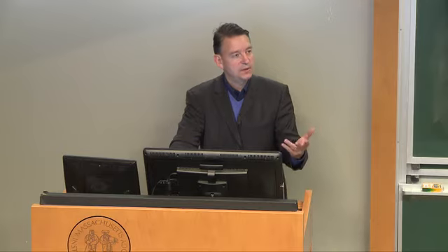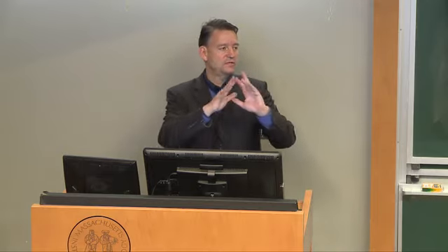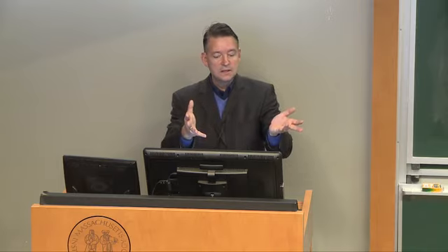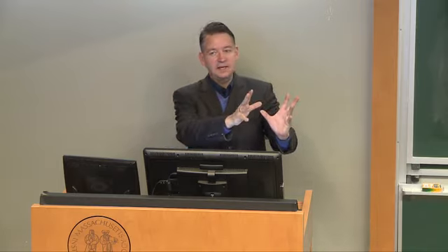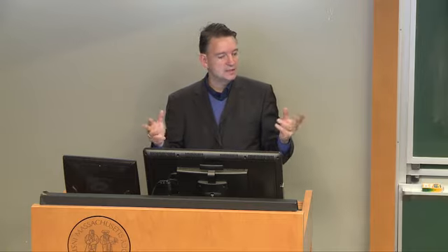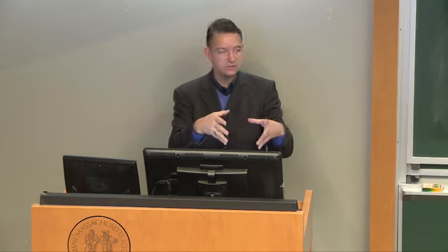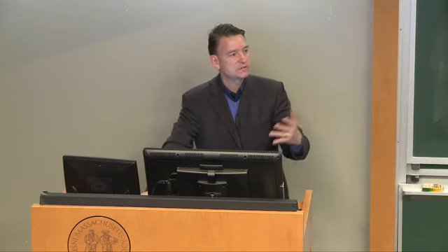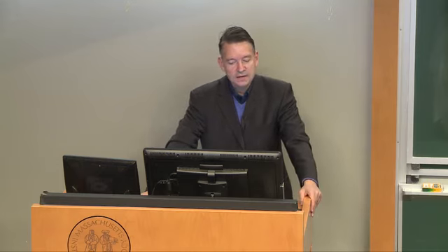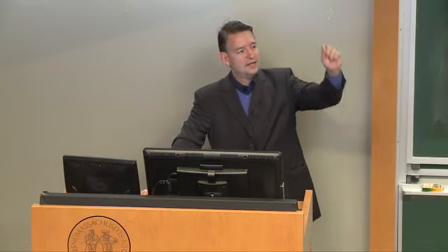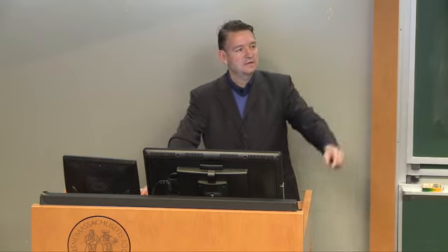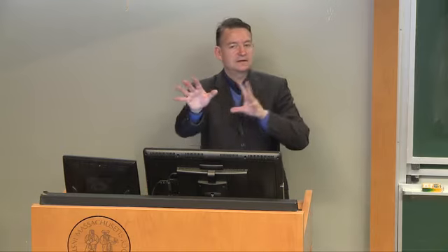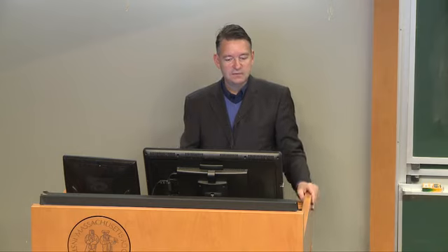Simulated tests, what do we mean by this? Simulated tests use dummy components. Maybe your full spacecraft or aircraft isn't ready yet. You don't have all the pieces. So you can still start testing, but you have to replace the missing pieces with dummy components. At least they should reflect the right mass distribution, but maybe you can do more. Simulated operations, so 0G versus 1G, is it representative? And what's often true is that you pass all your tests, and then you still have failures in practice, and the failures often happen outside of the test scenarios that you had tested. So you have to be ready for that, but try to avoid that.